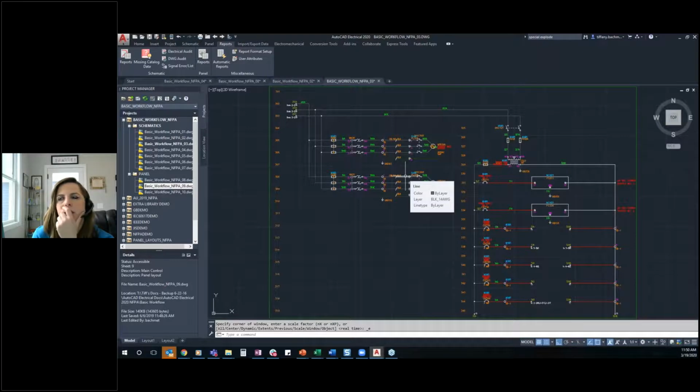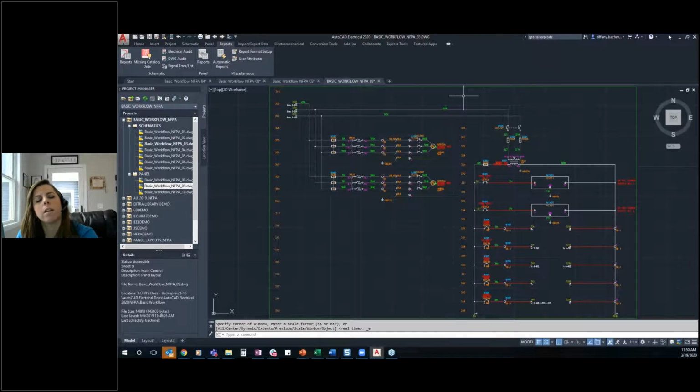And it doesn't matter. It's not really a wire number or anything that you can change easily. It seems like it's an actual behind-the-scenes identification number of what that terminal is, because if you have a layout with some terminals in it and you delete that terminal out, it still technically exists in that footprint terminal schematic, and it'll show up as blank until you actually delete it out. So I'm going to assume that it's that information that's causing my problem.